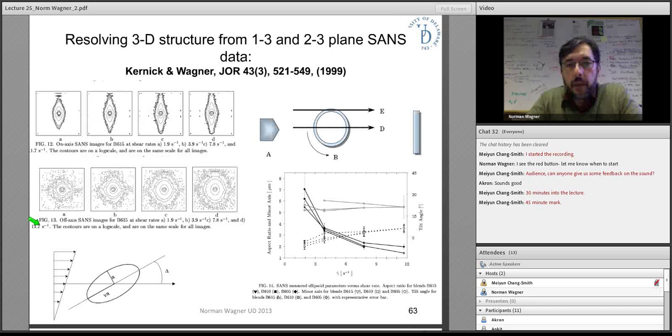So if you take a polymer blend and you shear it, under the right conditions, you can disperse the blend into droplets. In many materials, you would like to disperse this blend into the submicron or micron, let's say 10 micron or less size range. Under flow, these droplets will distort, orient, and you can measure that using neutron scattering.